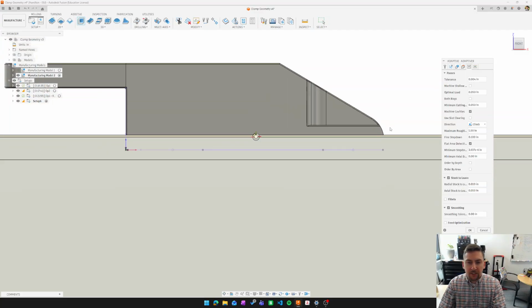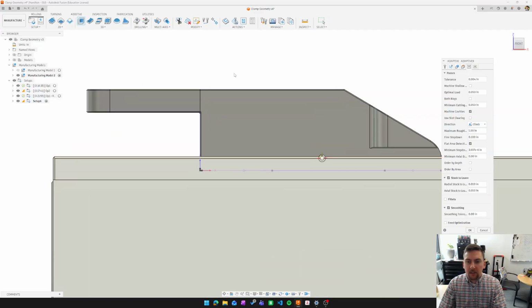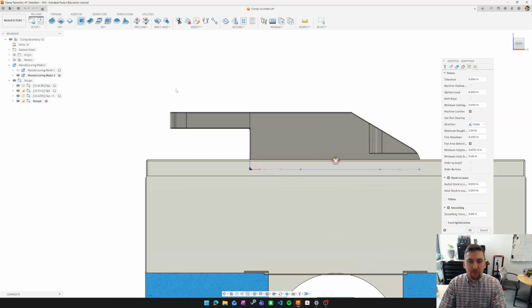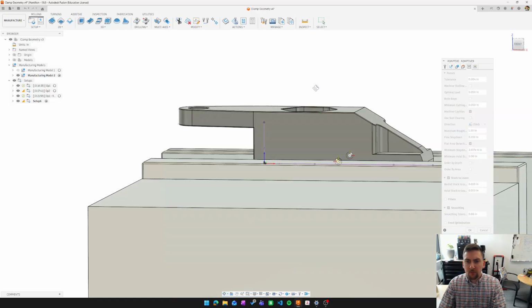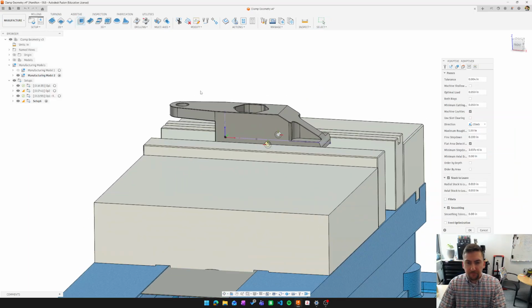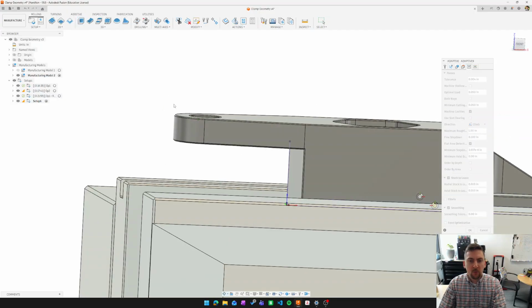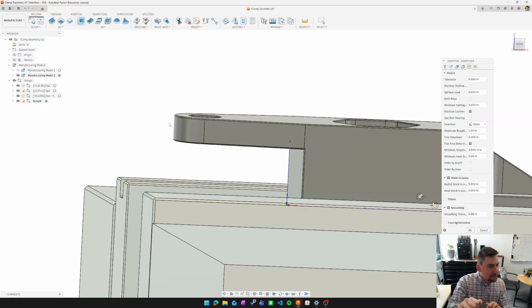And then one change I do want to make is the optimal load, or our step over, effectively. One of the reasons is this is a cantilever, right? When we start applying force on the end of this cantilever, it's like we've started using a can opener or a pop can.